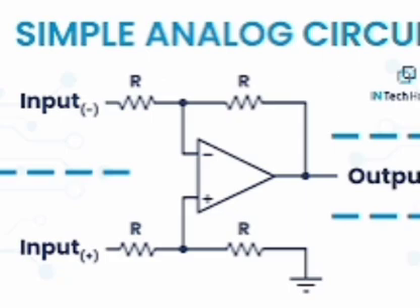Condition to avoid thermal runaway: a transistor will be thermally stable if dou Pc by dou Tj is less than or equal to dou Pd by dou Tj equal to 1 by theta, where dou Pc by dou Tj is the rate at which heat is released, and dou Pd by dou Tj is the rate at which heat is dissipated. For thermal stability, Vc less than Vcc by 2.